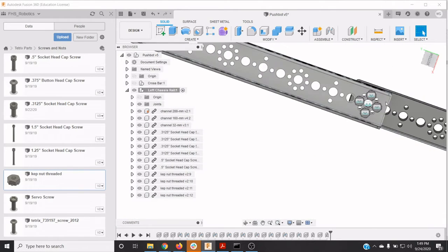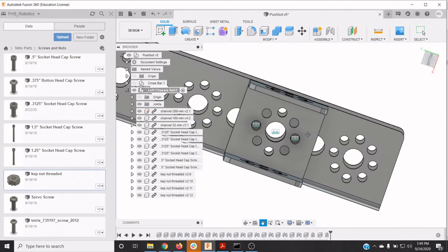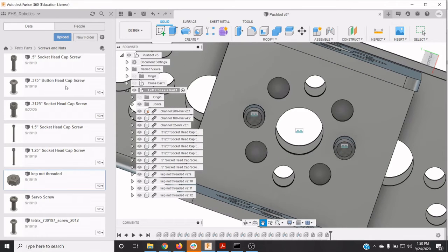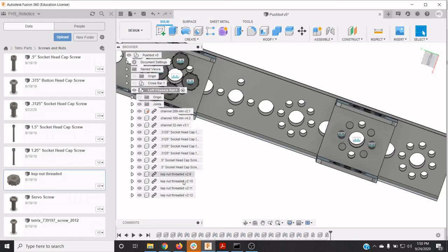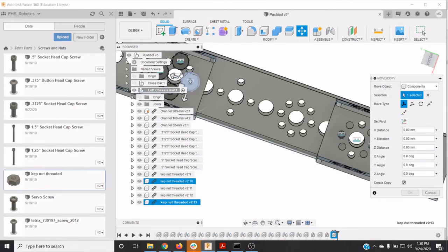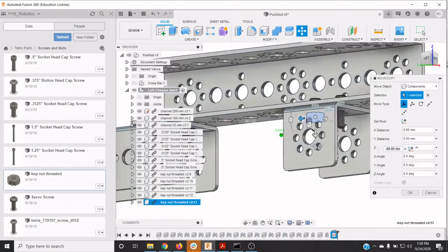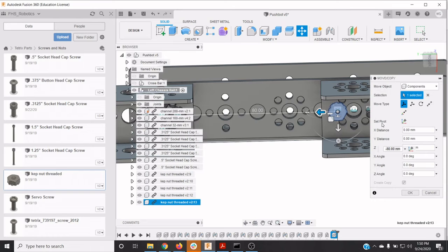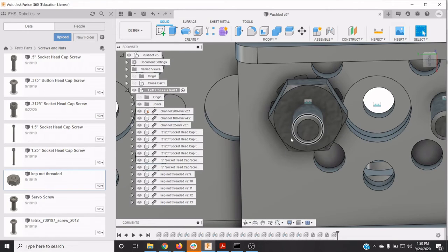We've got two others. Using the hand to drag my view around, wheel to zoom in. There we go. I think copying is going to be the better option here as well. Another move copy. Make sure you click create copy. Slide that guy right on down there. Check the view. Make sure that it's not intersecting anything else. It looks good. Yep, I like that. Let's capture that position. Yep, that looks good. And those are longer screws. It was throwing me off a little bit. They are sitting down a little further.